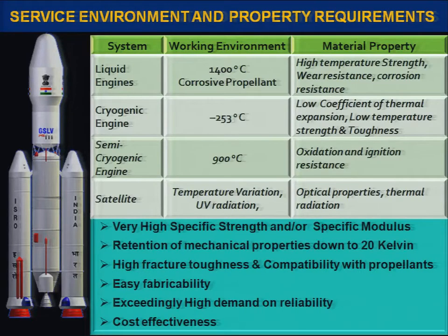Now, if you look at the service environment and the property requirements of some of these materials, when you are looking at liquid engines, you have to reach up to 1400 degrees, and there is a corrosive propellant. Then you require high temperature strength, wear resistance, and corrosion resistance materials. In the cryo engine, you have to go down to minus 253 degrees, requiring a low coefficient of thermal expansion, and low temperature strength and toughness materials.